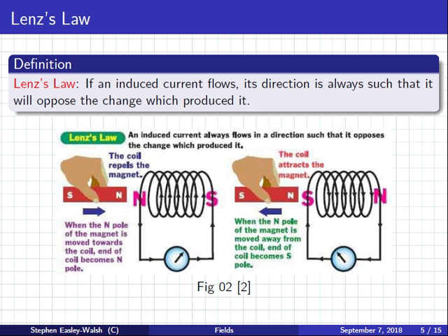So if you have all your wires stacked up, the magnetic field made by the top wire tries to push the charge in the opposite direction on the wire underneath. So in effect, you'll have more resistance than you need in the wire, and the wire starts to heat up. So if you're ever using one of these wheels connected to something, it's a good idea to fully unwrap the wheel for safety. Otherwise it'll overheat. Lenz's law is actually the reason for this.